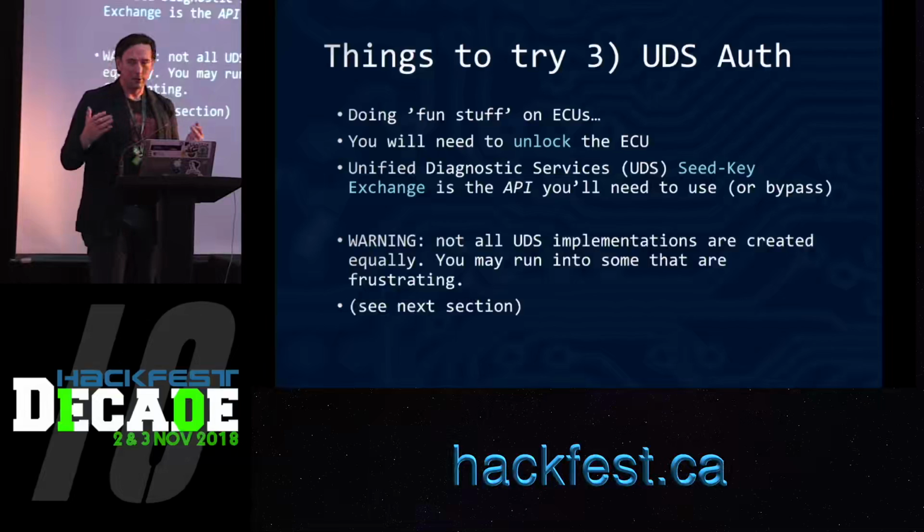You'll see it evolve. Also from previous work, we know the loader loops. This is kind of like the C runtime stuff. I know that it goes into that flat file in Flash and copies it from this yellow address to this blue address, and I also know the length of it is orange. So I'm going to put more stuff into our config file.